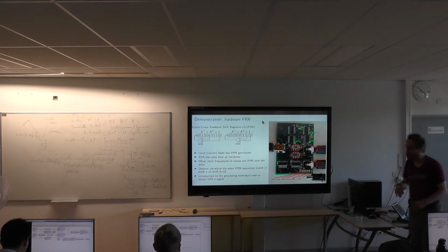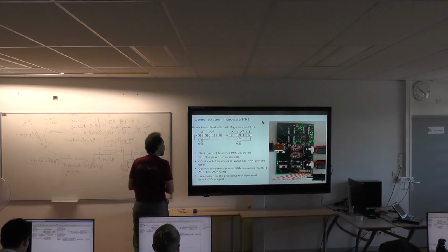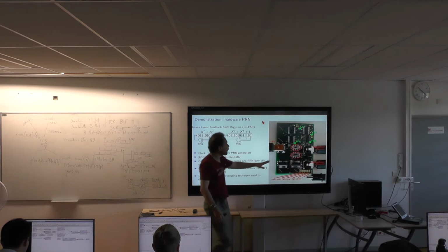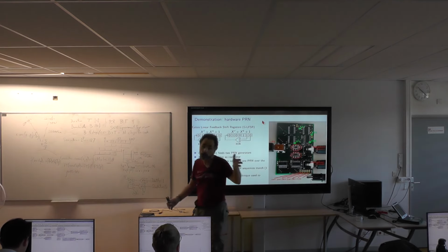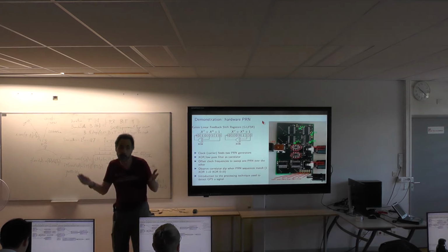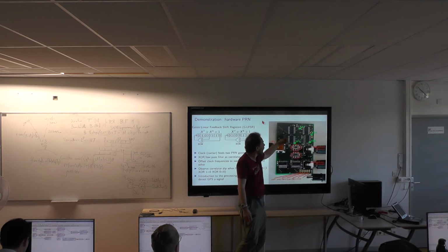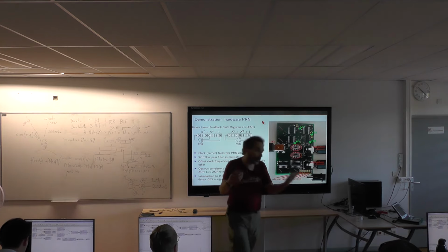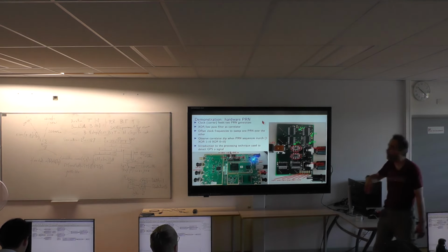Just let me mention that previously we used to perform this with analog hardware. GPS was designed in the 70s, running in the 80s, so of course these all use technology that is quite easily accessible. You can actually buy shift registers off the shelf, and you have XOR chips off the shelf. Now in 2025, you would no longer do this in discrete components. You would run this inside your FPGA.